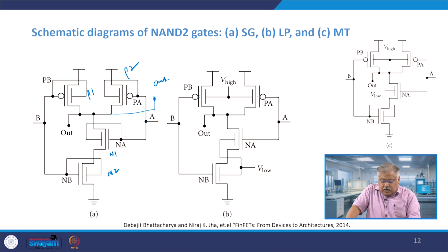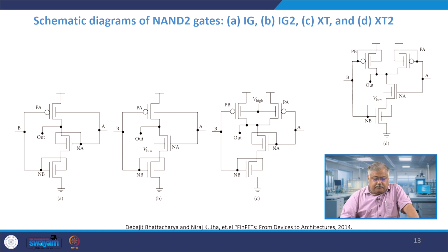So, you can see here both my substrates have been given an extra bias, right. So, you are actually giving a VBS, bulk to source potential, which will lower the threshold voltage and give lower power, right. Same thing happens on the right hand side for the other design.